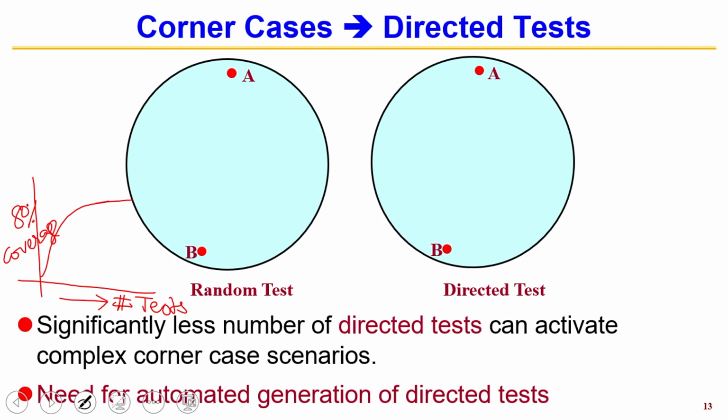But normally, if the branches have a rare condition, where the condition itself is extremely rare, you can keep running, but coverage is not going to go up too far. So that is why, whatever companies can achieve by constrained random, the remaining they try to cover through various other mechanisms. It may sound funny, but they actually use some of the manufacturing tests also, just to increase the coverage. Then people would add some directed tests, some ATPG tests. Directed tests people would write manually. If I know which branch I need to cover, they try to figure out what the initial condition has to be for this branch to be activated, right.